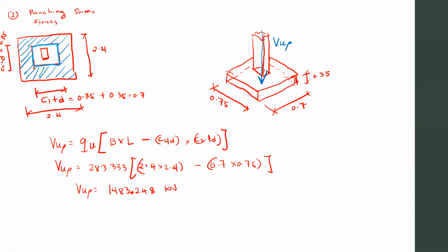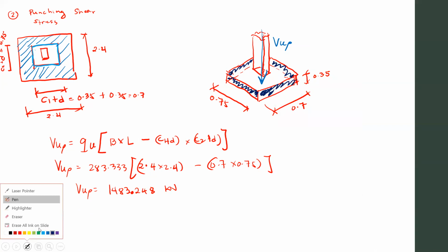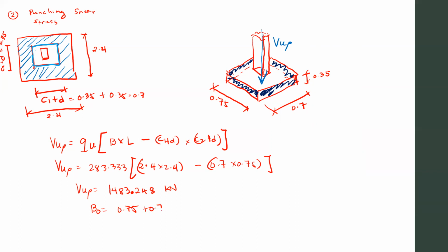Okay. So, to determine the shear stress, okay, meron ka ng shear load, hanapin mo yung shear stress, ano ba yung mag-cause ng shearing area? This is your shearing area in punching. So, basically, parang area 1 plus area 2 plus area 3 plus area 4, or pwede, kunin nyo yung perimeter multiplied nyo sa depth. Okay? So, kunin muna natin yung perimeter. Ang perimeter natin, which is denoted as B sub O, is equals to 0.75 by 0.7 times 2. That is 0.75, 1.45, that is 2.9. Tama?